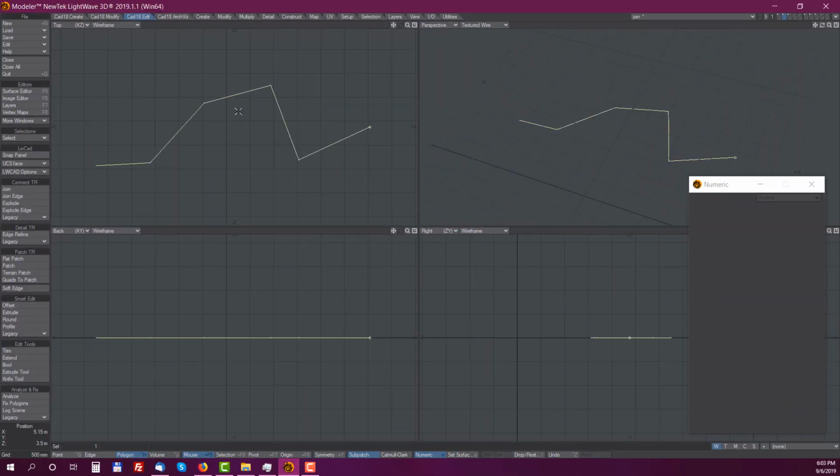In the second example, we have one single polyline. If I use explode on everything, then each segment is separated from the original line. So now we have each segment as a separate curve. I'll join it back, and if I use explode edge, we have 2 options. We can explode to segments or to curves.